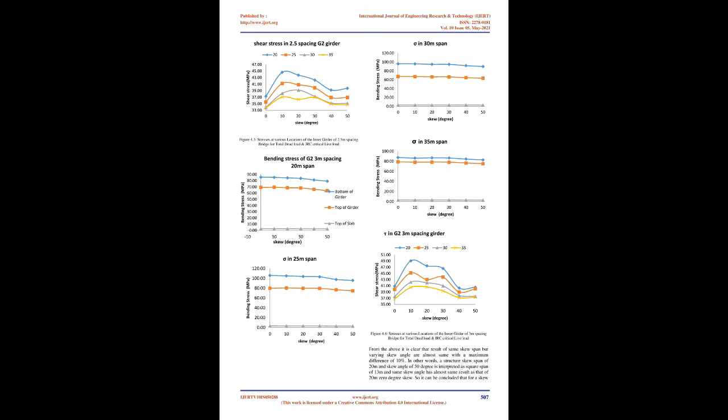Results and discussions. In order to obtain meaningful results for bridge analysis, i.e. moment or force, an appropriate interpretation of the results is essential. To calculate the stress from the analysis, the moment in the girder section has to be established. The moment at a particular section is the resultant of girder moment in the beam member and deck moment in the cross members. These moment and shear force values are obtained directly from the analysis of the bridge using STAAD.Pro software.